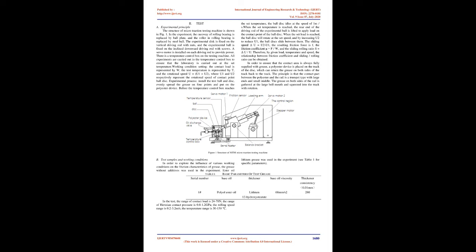[10] The research results of Ahara and Dowson on the double ball tester show that the film thickness in the state of lack of grease is about 70% of that of the base oil in the state of flooded oil. [11] Ken et al. studied the change of oil film thickness with time under constant working conditions, and observed the effects of rolling speed, temperature, base oil viscosity and thickener content on the degree of lack of grease.